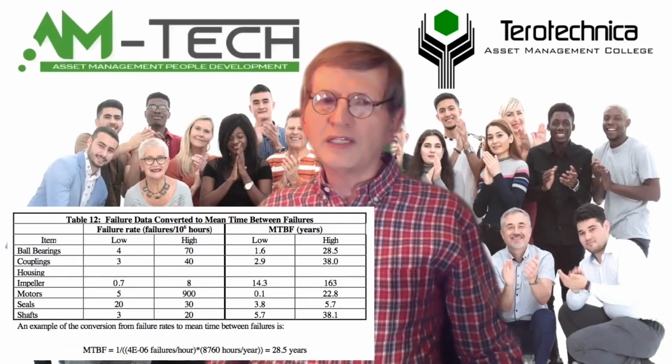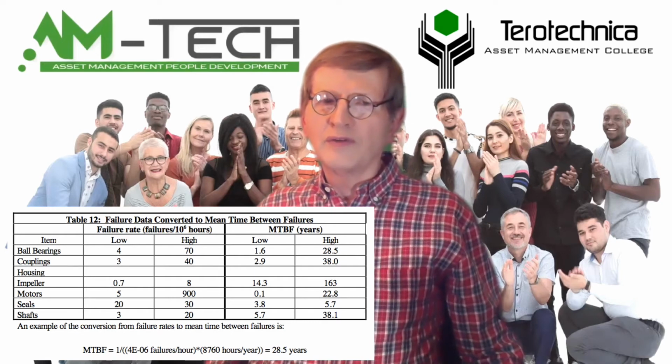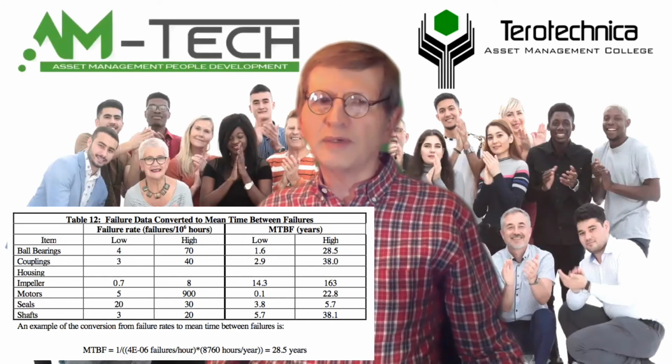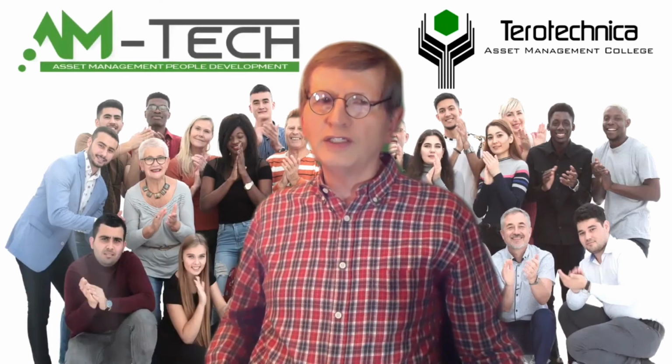Step 10. Study the risks of high-cost items and occurrences. The failure rate data, or more correctly, the ROCOF, that's the rate of occurrence of failure data, in Table 12, is again sourced from Bloch, 1994 and 1995. There are quite a number of reliability databases where such data can be obtained. The calculation below illustrates how such data can be used to calculate the mean time between failures, the MTBF. Note, there is no data for the pump housings. In such a case, one must use own experience or other sources. One-stop shopping for the ROCOF is not possible.